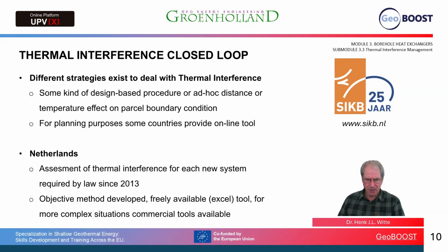In the Netherlands, and the little icon on the right shows you the SIKB, which is the Dutch protocol holder, we have a formal procedure for assessing the thermal interference between systems, which has been required by law and in effect since 2013. This objective method, which is based on the finite line source solution, is freely available as an Excel tool, but for more complex situations, commercial tools are also available.